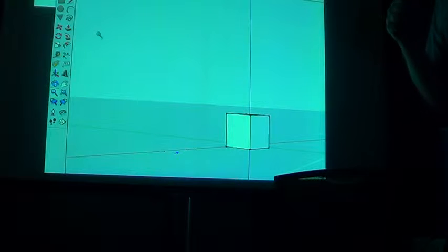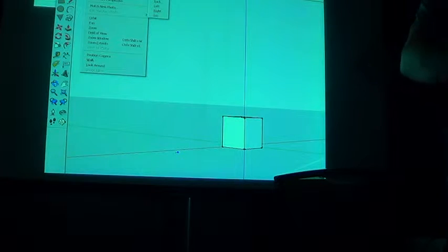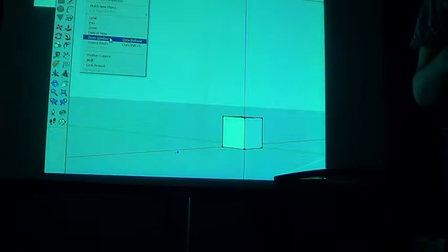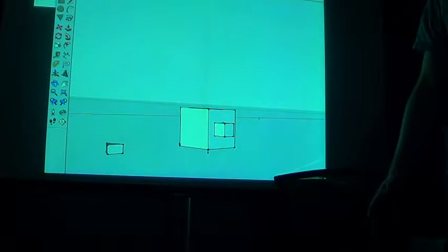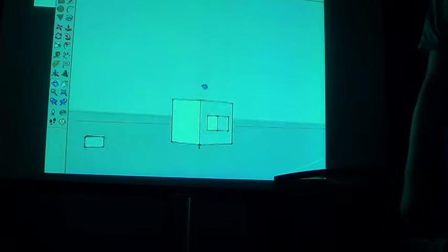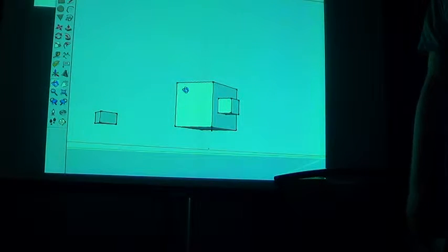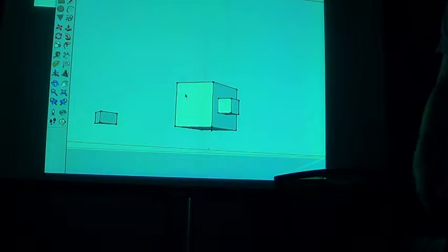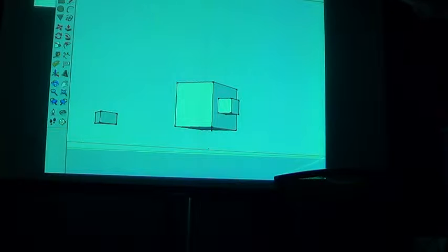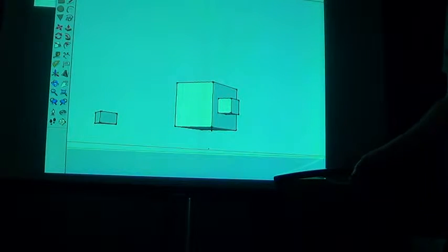What you're doing is printing part of the layer in one material, the printer pauses and moves off to the side, you unload and load the other material, feeding it down through. Once it's ready, you tell the printer to resume, and it prints the other part. You have to do that for multiple layers. In general, it probably takes 2 to 3 minutes every time you change filament. So if you have an object that's 200 layers, it's going to take forever. It's not worth doing on a single filament printer. Some printers now have two nozzles, and the commercial machines can have multiple nozzles and switch material pretty easily. The other thing is that with a single nozzle, you have to wait for the temperature to change for that material.